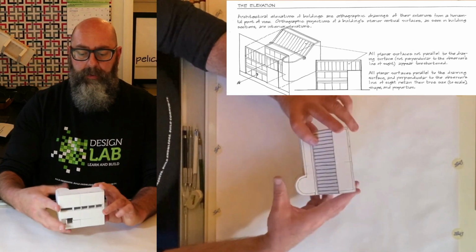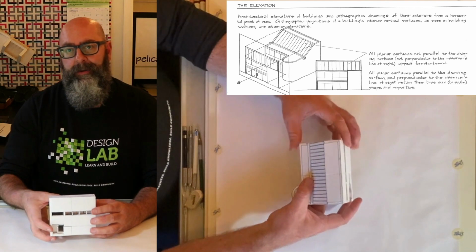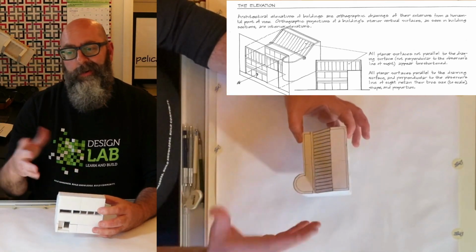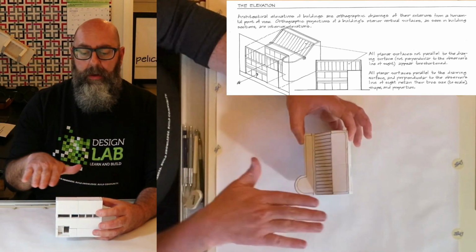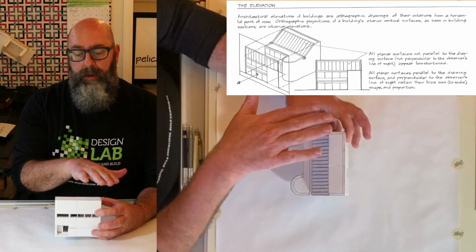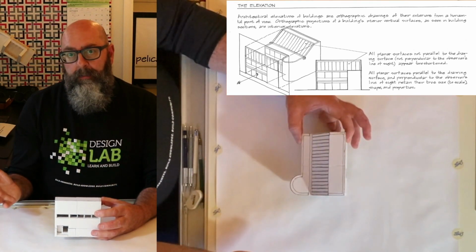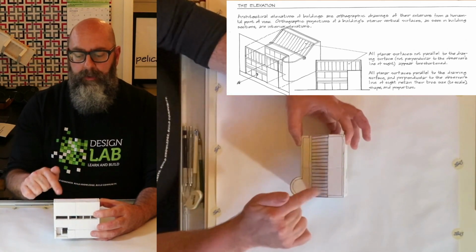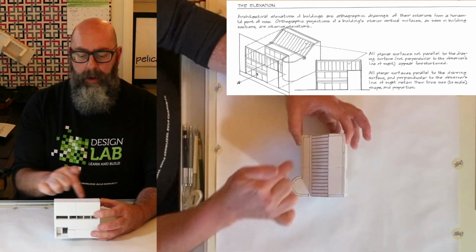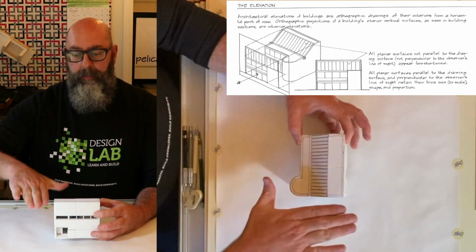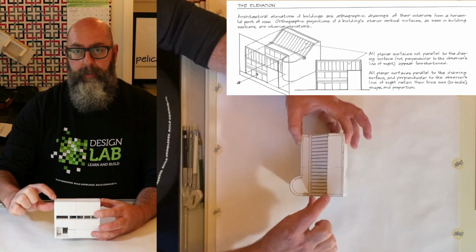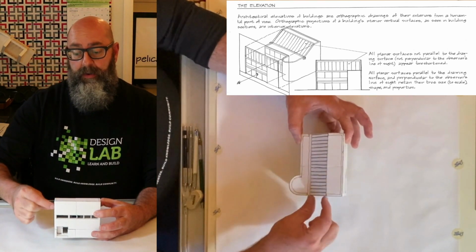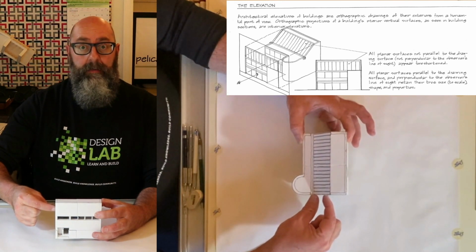Now, some people say that the roof plan is an elevation. I call it the fifth floor. It's actually, you'll draw it as a plan, but it's kind of like an elevation. So you draw the flat part, you draw the slope part, and you draw the other flat part, but when you draw it in plan, this sloped bit turns flat.